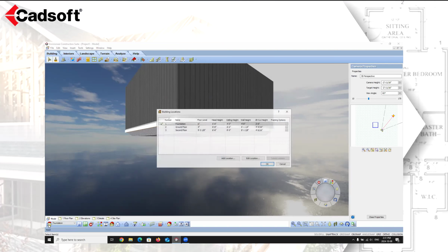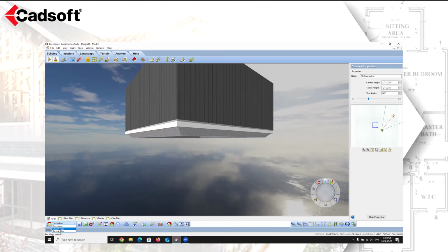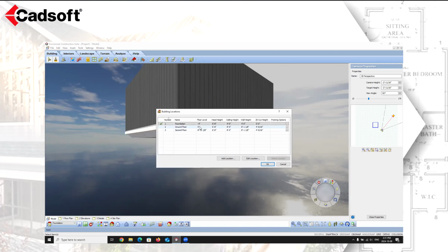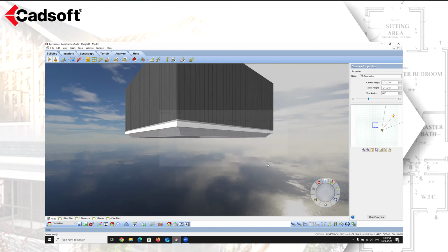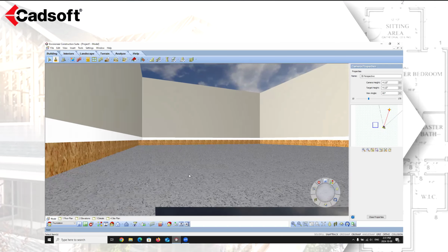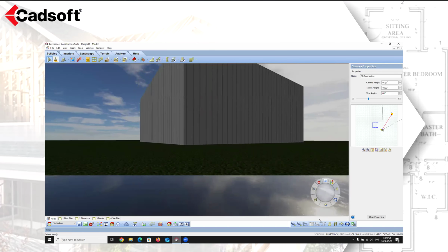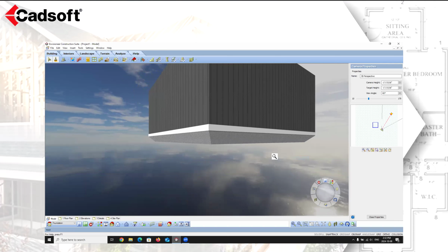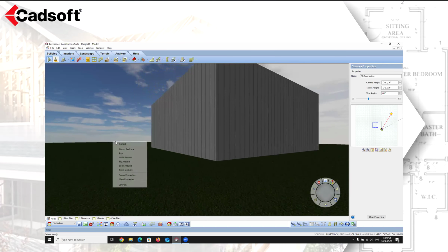And actually, we probably want that to sit at -4 because we want the slab to sit down. And then we want 4. And there our walls are now going to sit on top of our actual floors. Now this particular wall has a drop exterior face assigned to it, so it's going to show down inside the foundation there. So we may want to adjust how that wall is being adjusted.